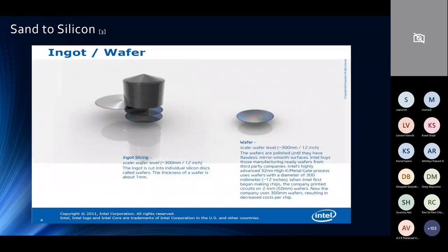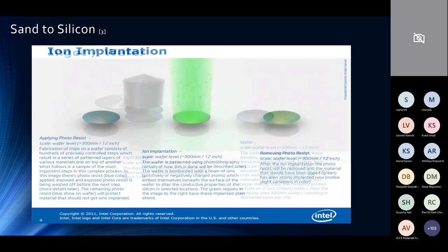After you get that silicon cylinder structure, you then start sawing it with a diamond saw to form single wafers. So when people talk about wafers and all that, this is what it means. This is a silicon wafer. This silicon wafer is the place where you fabricate your chips. One wafer can house hundreds of chips, depending, of course, on its size. So one wafer has a number of chips, all of the same design.